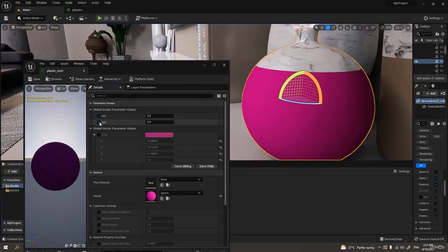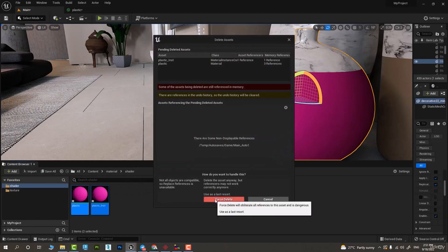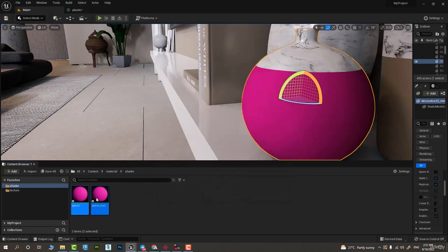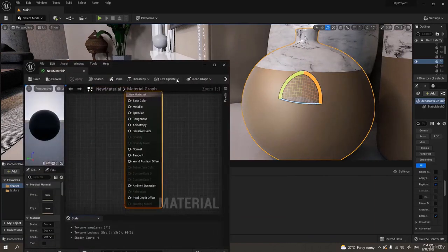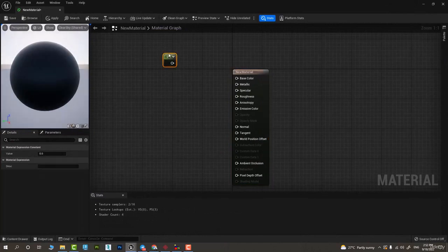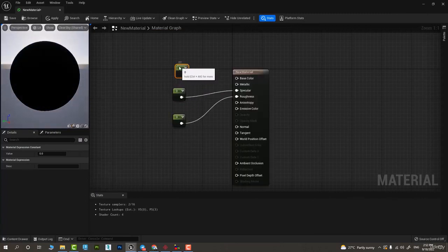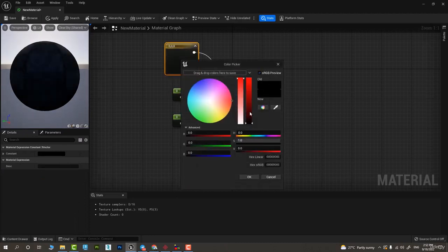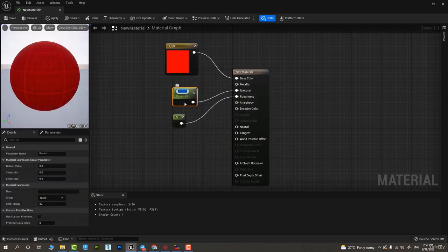Again, I do not see the reflectiveness and the glossiness that I want, and it should have, so there's a problem somewhere. Okay, so this time I'm gonna delete both of them, and create everything from scratch, make a new material file. Let's leave it at new material name, go to the slate. Let me just create these black and white tabs here, a couple of them, one linked to roughness, one linked to specular, another one linked to my base color. The one for the base color is a 3-color combo like we talked about, so maybe select red for it at this time.